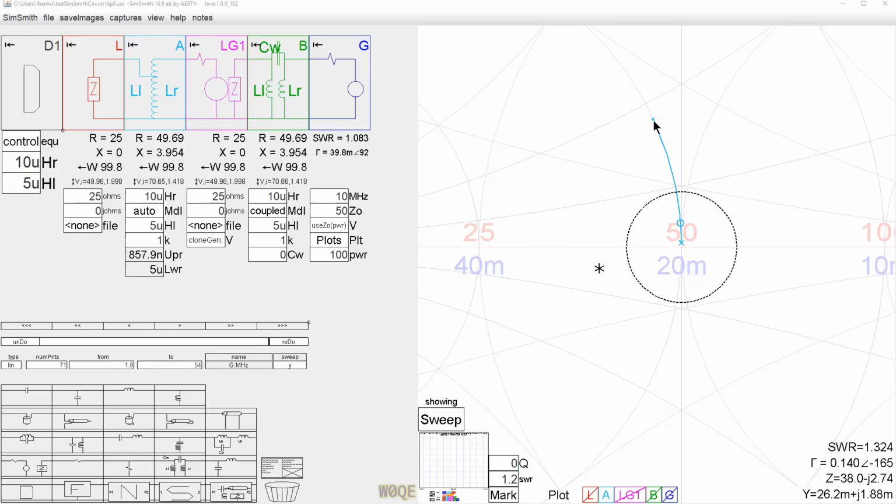This is the 1.8 megahertz impedance. We can click on this plot, or this chart down here, and change the meaning of it. So we start with impedances. This converts it to a parallel impedance form.